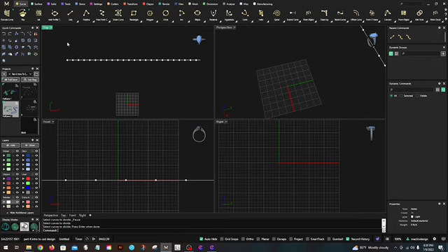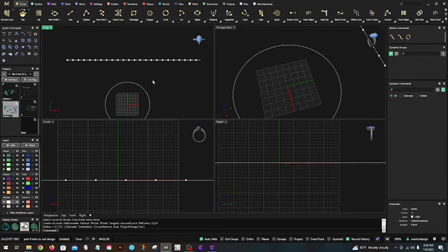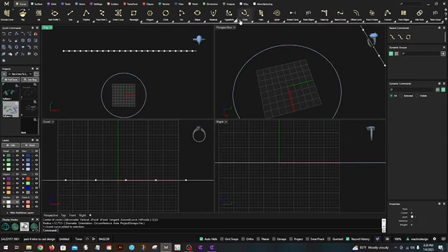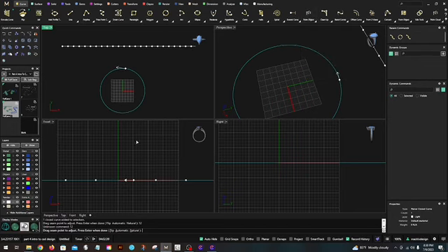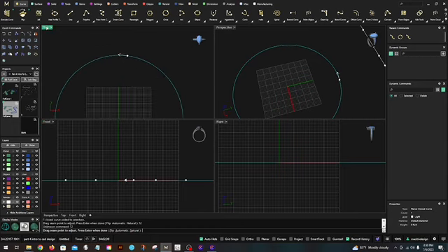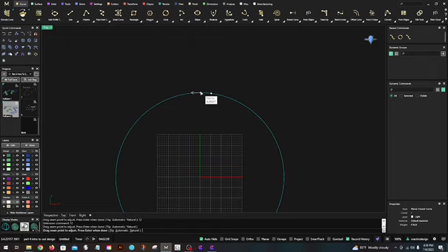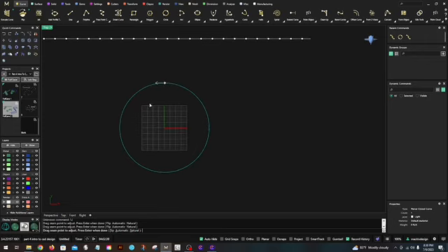So let's do another one. Let's do a circle and see if that'll do it. All right, I'm going to divide curve by number of segments. That's the one that I have used a lot. So there we go. And let's do 12. Oh, drag seam point to adjust. I need to follow directions. There we go. So I want that centered. There we go. And press enter when done. And I want 12.